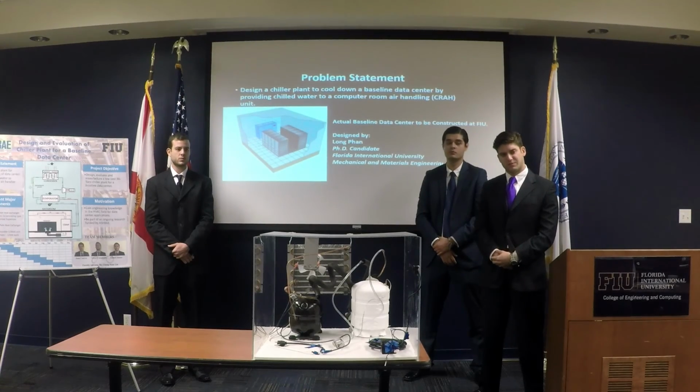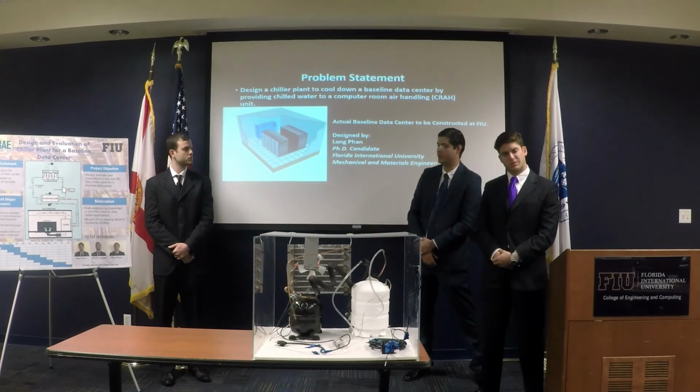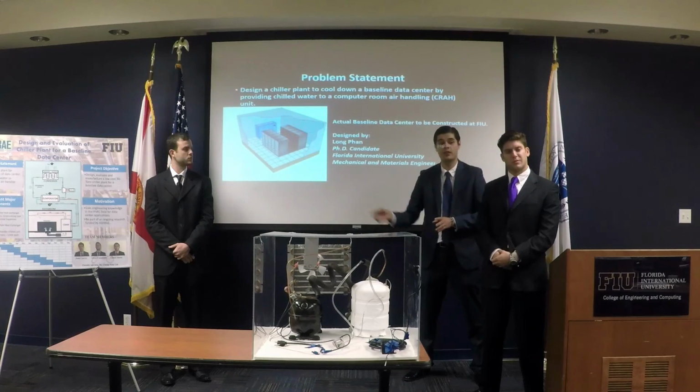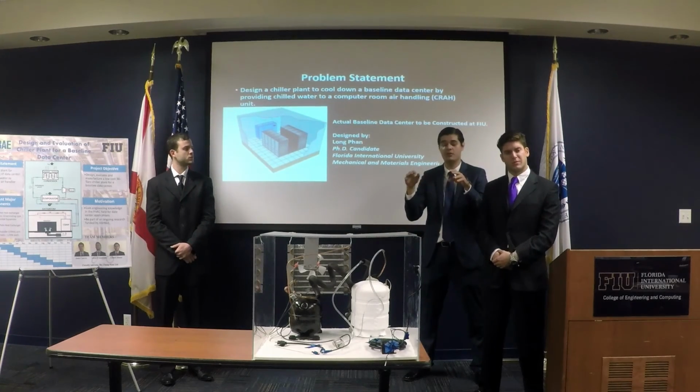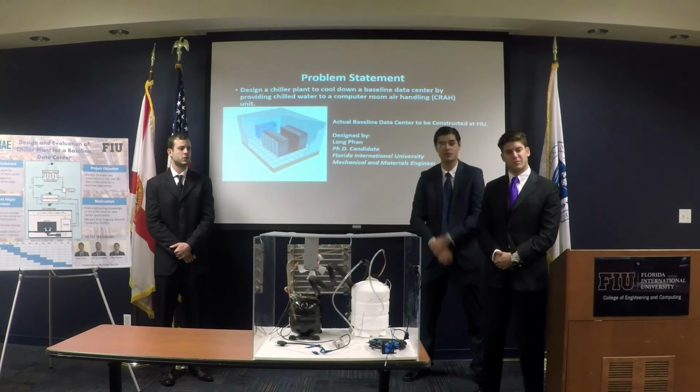So did you use a factor above your maximum requirements to go over? For example, when you were doing your calculation for how many BTUs or how many tons to use, did you just go by the maximum, or did you multiply by a factor, like 20% more? Well, the maximum will be 120 kilowatts, and our actual calculations will give a maximum of 131 kilowatts.